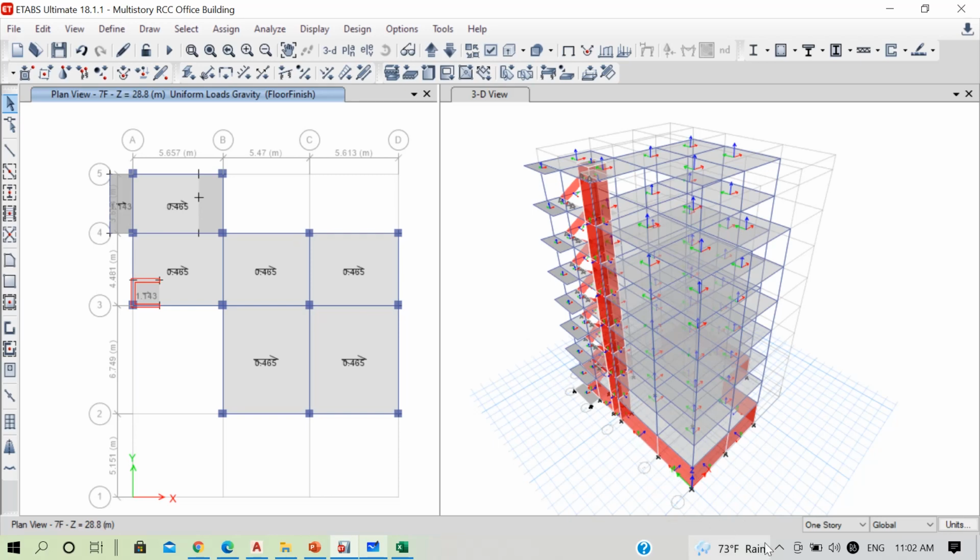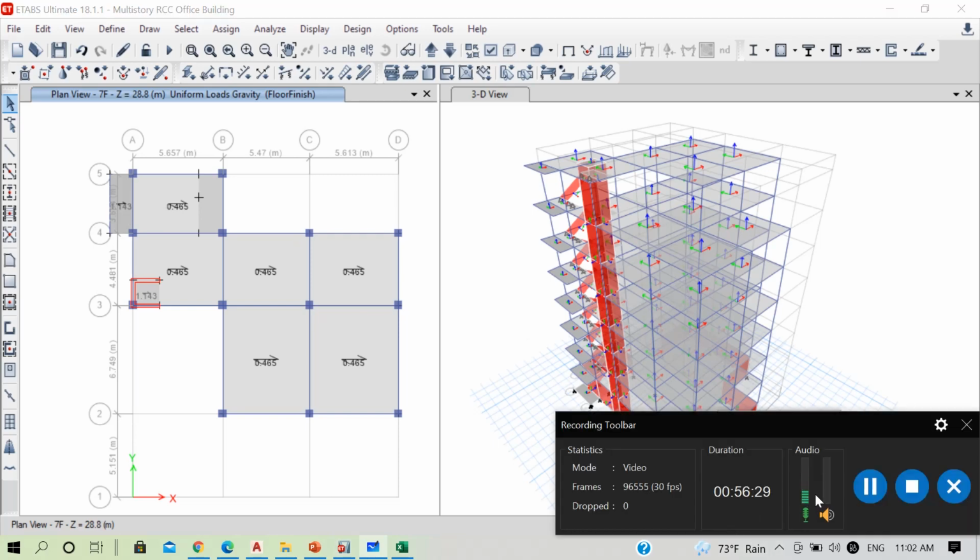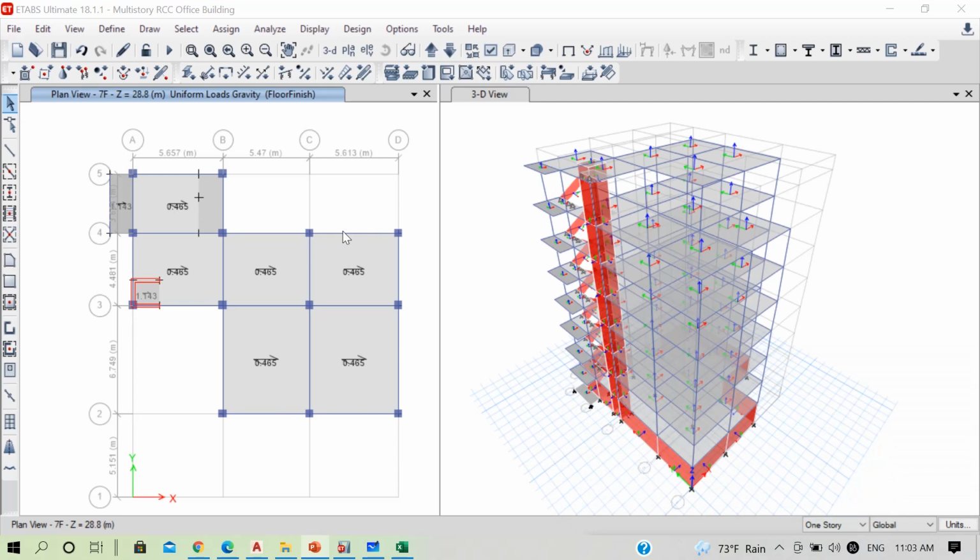So how we do this is, 2000 liters of water means we have 2000 kg of water, and we convert this 2000 kg into kilonewton per meter square. First convert 2000 kg into kilonewton. So 2000 into 9.81 gives 19,620 Newton, divided by 1000 is 19.62 kilonewton.